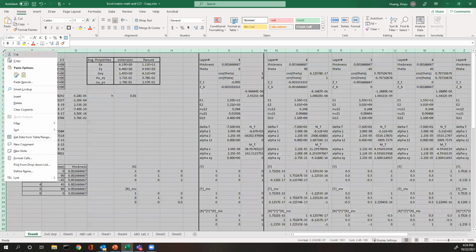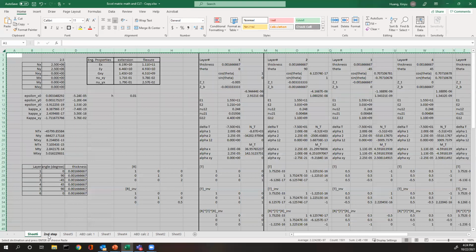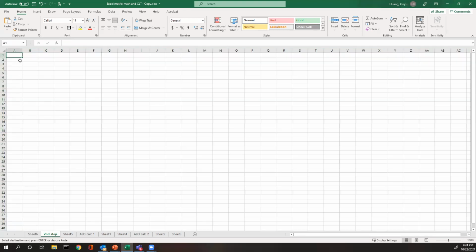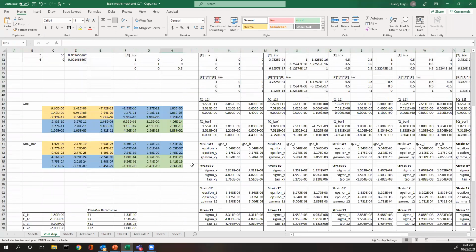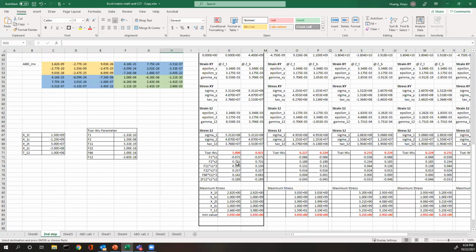I can copy the whole thing over. This first spreadsheet remembered the threshold when the first ply cracking occurred. Then I copy that over here. I calculate. At this point, I would apply the reduction. The reduction is you effectively simulate the damage due to the 2-direction tensile stress cracking. You basically reduce your stresses.